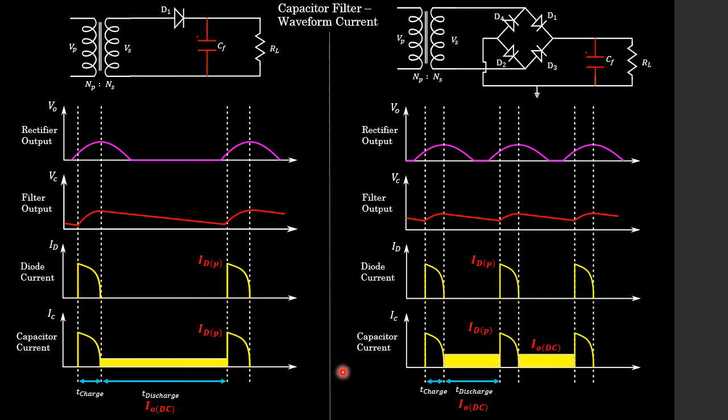And another thing to note, students, is the diode peak current that we see. The diode peak current occurs during the charge cycle, and when our diodes are forward biased, they are going to experience some peak current, and we'll look in a future slide to see that that peak current needs to be kept at a specific value so that we don't end up damaging our diodes.